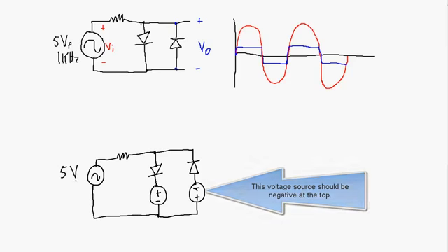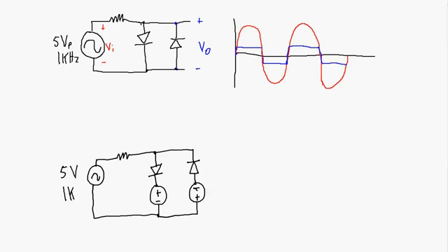So we're going to have our 5-volt input signal again at 1 kilohertz, although the frequency in this case doesn't really matter so much, because I don't care about the time scale. What is important though here is what are these two offsets? Well, this first one is going to be at 1.3 volts. The second one is going to be at 2.3 volts, but you see it's in the opposite orientation, so relative to this one it's negative 2.3 volts. And then I'll have my output over here.